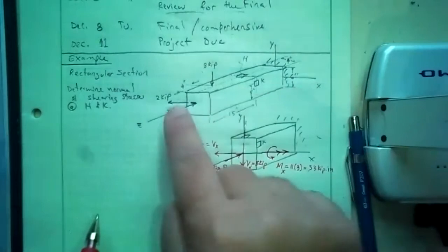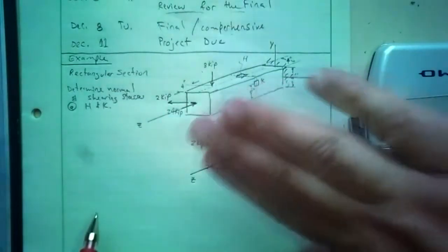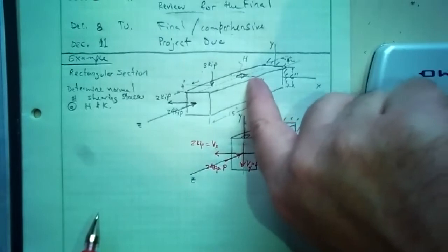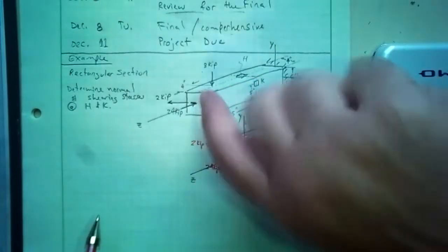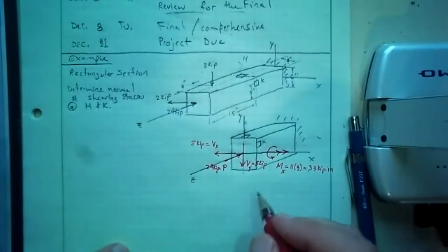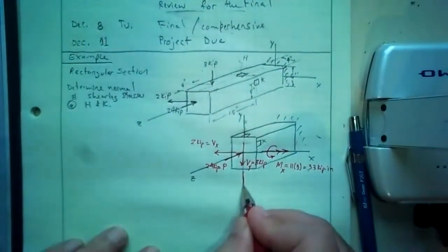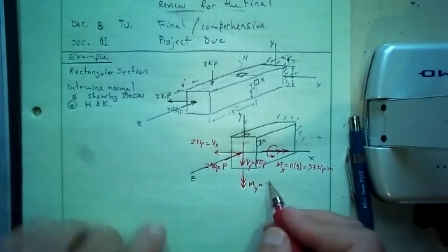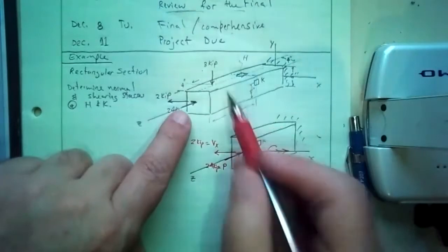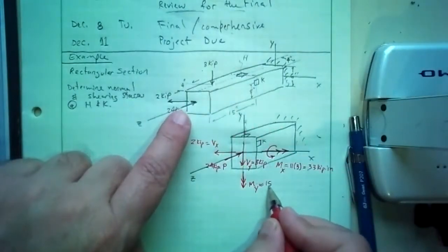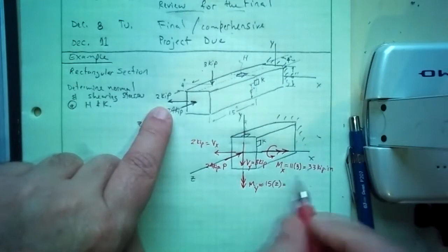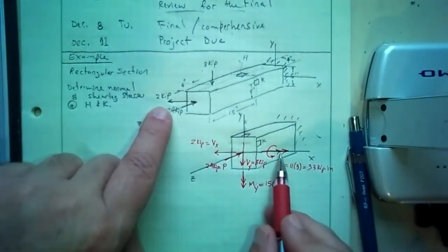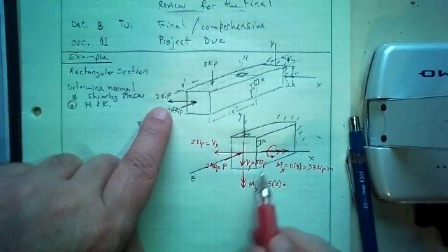And then the same thing for that force. R, again, R is going from here, from where the cross section is, all the way to where the force is applied. Fingers of the right hand, cross F. My thumb is pointing down, so that's a negative Y. So I have a moment, which will be, now this distance is 15 inches times 2 kip. So I'm not writing in terms of, obviously the direction is defined by these arrows, right? The direction is defined by the arrow.